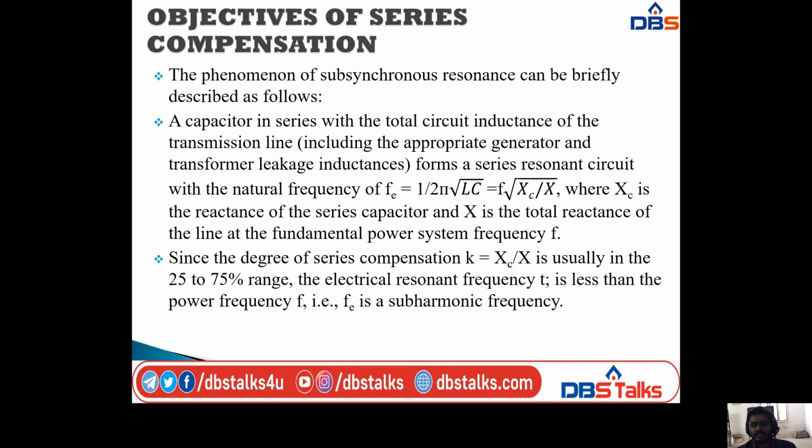Since the degree of series compensation, K, equal to Xc by X, is usually in the 25 to 75% range, the electrical resonance frequency Fe is less than the power frequency F, that is, Fe is a subharmonic frequency.